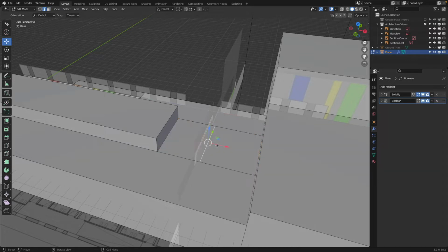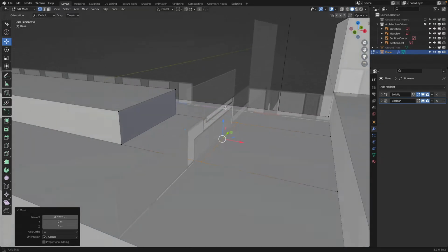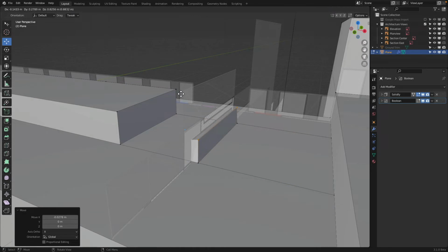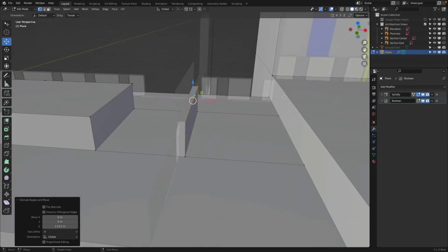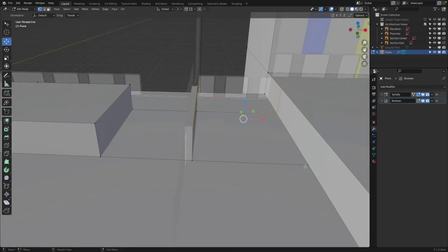This line now I will select, or maybe via the points I can see it. Oh, yeah, this is actually perfectly on it. And now I do the following. I press E and Z, hold Control and snap it to there. K, here, click Z and click. You see how I'm cutting these edges. Click with K, Z, click and enter. Because all I need to do is this edge here.